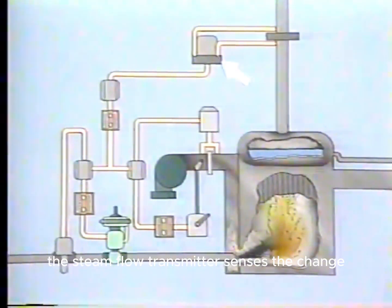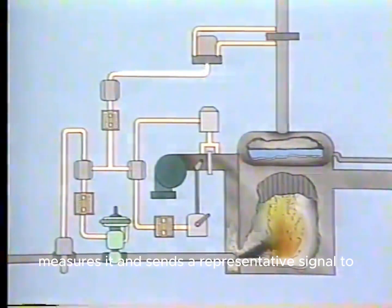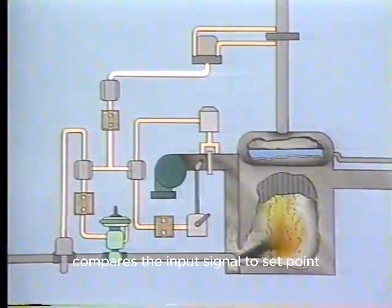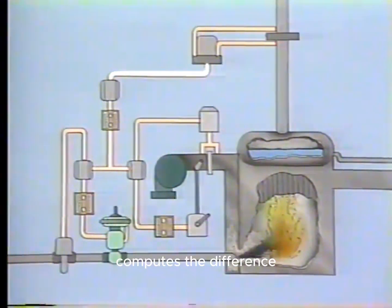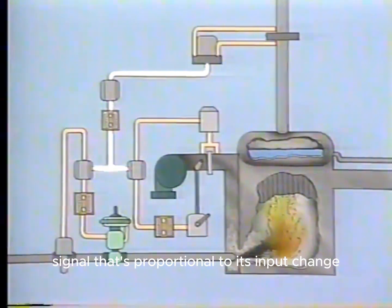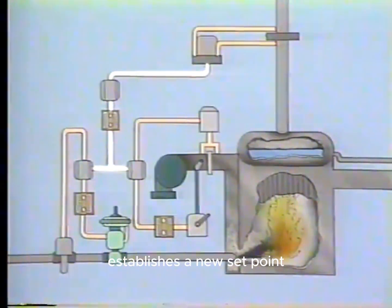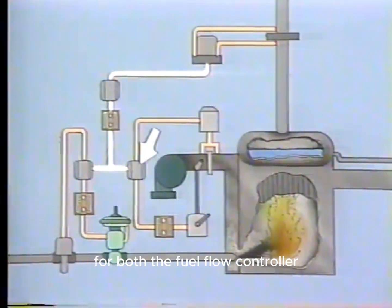When the demand for steam changes, steam flow changes. The steam flow transmitter senses the change, measures it, and sends a representative signal to the master controller. The master controller compares the input signal to set point, computes the difference, and produces a corrective output signal that's proportional to its input change. The corrective output signal establishes a new set point for both the fuel flow controller and the airflow controller.